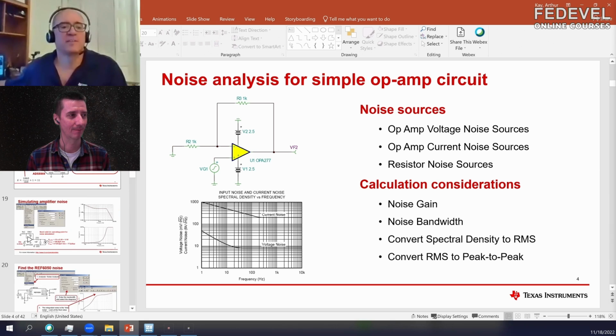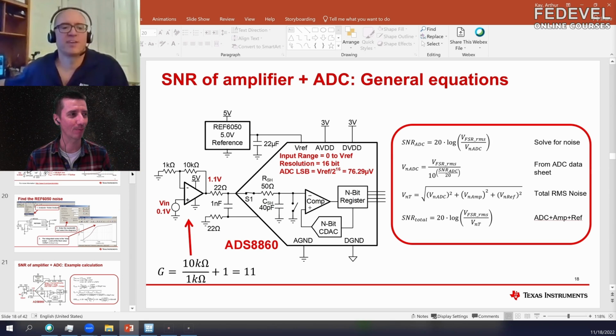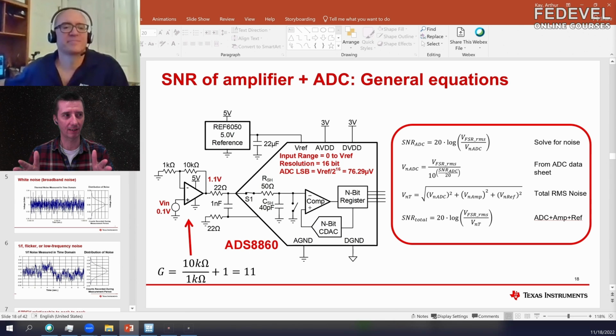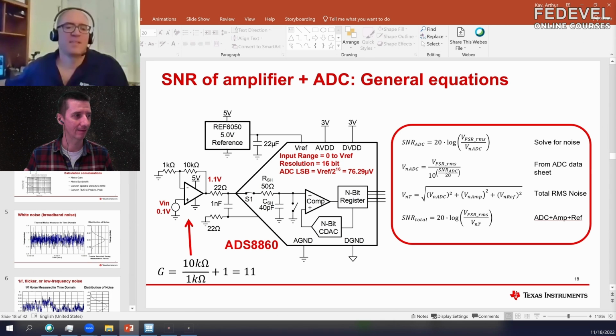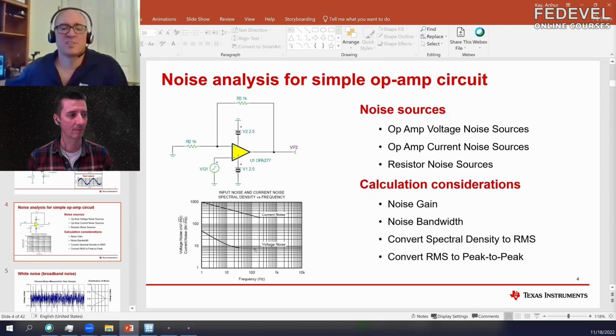One other thing I could mention is broadband noise. Let's go back. Broadband noise, that's the standard noise, correct? Yes, that's the noise that a resistor would have. This broadband region is what a resistor would have. There are resistances internal to the amplifier and other semiconductor-type noises, and then there are other noise sources that generate this 1/f.